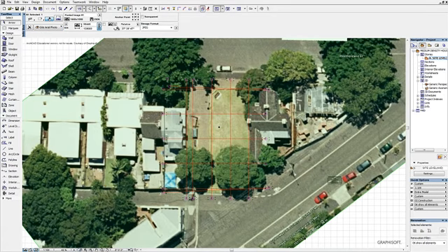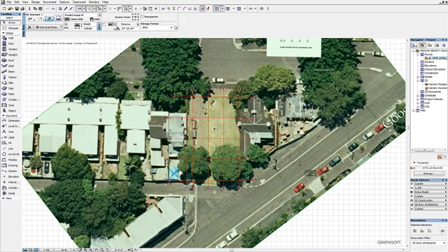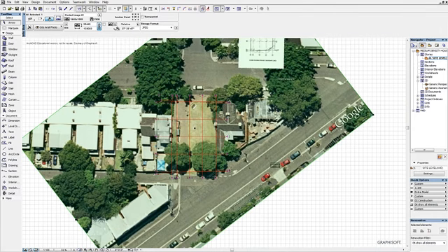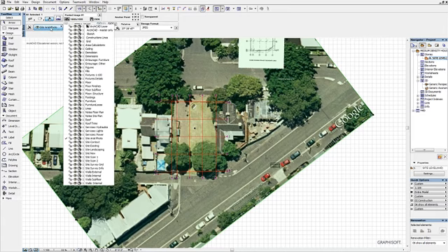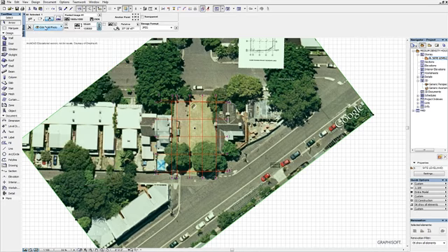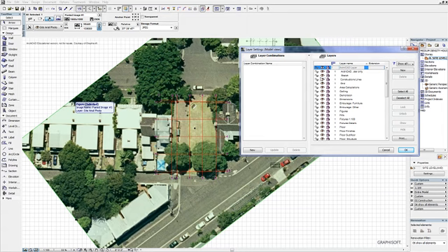When anything is selected on the grid, such as this image, which is selected currently because it's highlighted in green, you can move those selected elements between layers. This you can do by just clicking on this button in the information box. However, to actually hide layers, or unhide layers, or lock layers, or unlock layers, you must press Ctrl L to bring up this window, and to hide and unhide, and to lock and unlock, and also to create new layers or to delete layers.